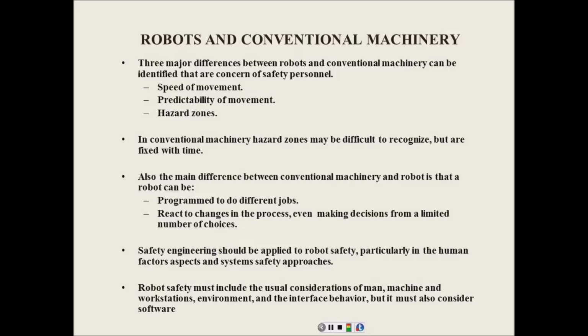But you got to understand, these robots are sensing their environment, and they can do different things than they normally do. So if something happens that doesn't normally happen, but it's been anticipated by the programmer that it might happen, then they might have that robot do something that you're not used to seeing it doing, right? You understand? And then you get in that robot's way, and it's doing a high-speed move. There is no way in the world you're going to get out of the way of that robot.